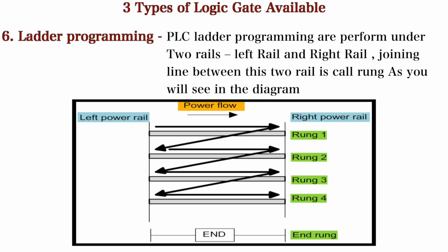There can be many rungs in a ladder diagram. Each ladder diagram is ended by an END rung, which you do not need to program. It just signifies the end of the ladder diagram.